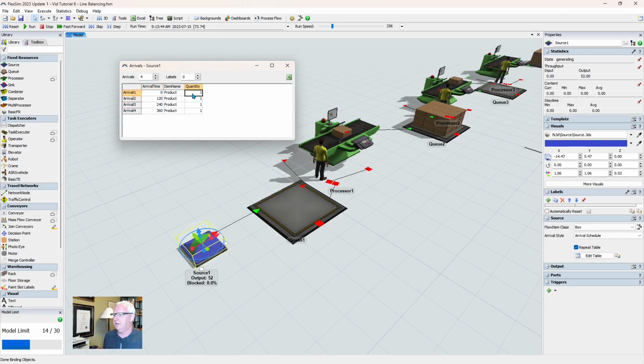Now, it means that I have to deliver 2 hours worth of material. And I think I found that about a part every 1.4 minutes gives me a nice balance. So now I need to have 2 hours worth of parts at 1.4 minutes.